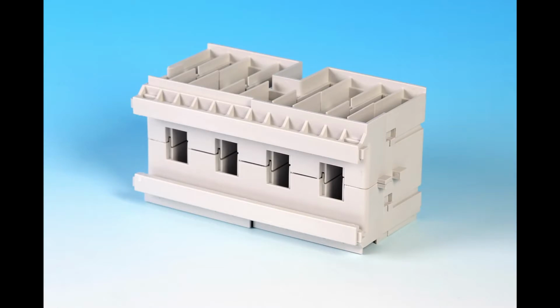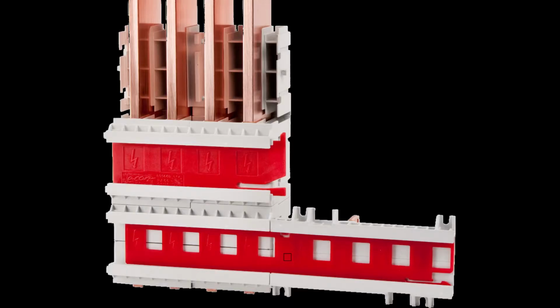The busbar module. The busbar module takes flat standard busbars up to 60 mm by 10 mm, optionally also up to 200 mm by 10 mm. The busbar module realizes full insulation of the vertical busbars from face to face as well as from face to earth. Modular construction allows easy installation without the need of any tools.